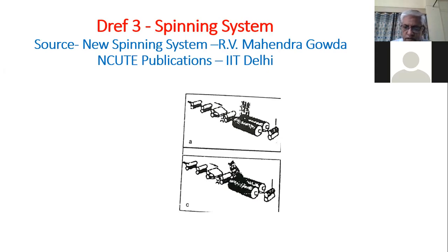So this kind of system opened the doors for the two component yarn or sheath structure, just like coarse spun yarn. And we can make different combinations of this coarse spun yarn. But here also the range was limited to up to 18 count only, although the speed was high, 300 meters per minute.